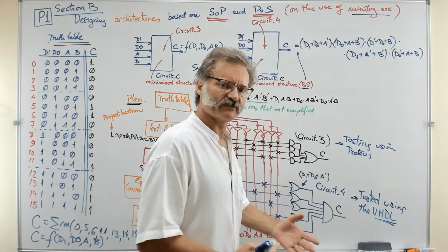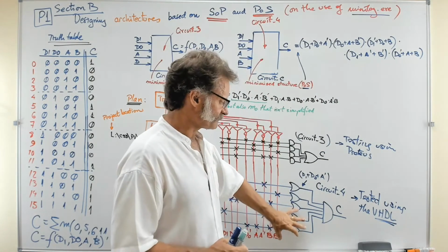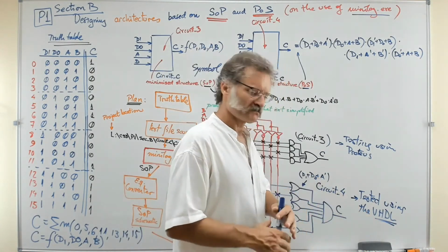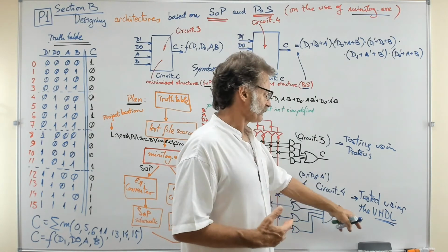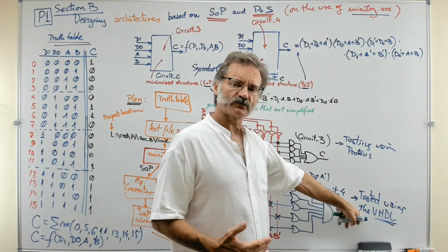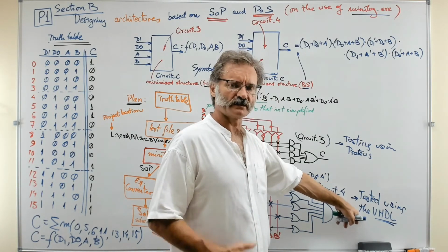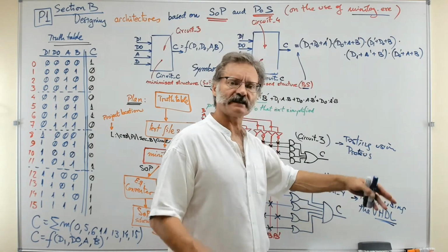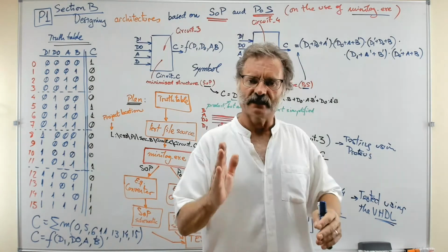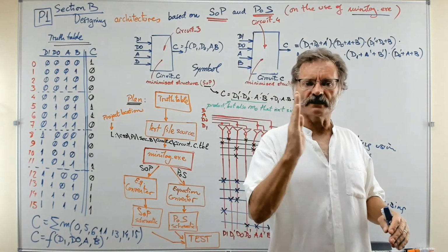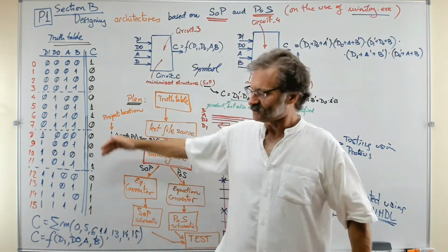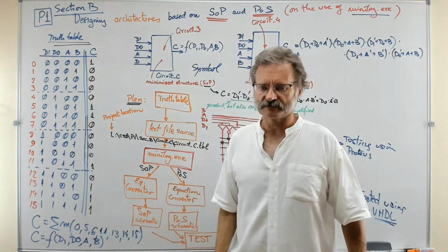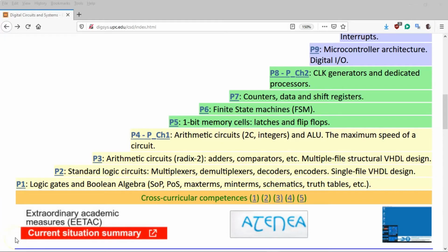It's time for checking the circuit that you have invented using the VHDL, just another opportunity for using the synthesis tool, the Quartus Prime synthesis tool, for example, and the ModelSim project to get a final timing diagram. And by means of the cursor in time, you can just annotate the full table and check if everything is all right. Testing the circuit, for example circuit 3, using Proteus is that simple.